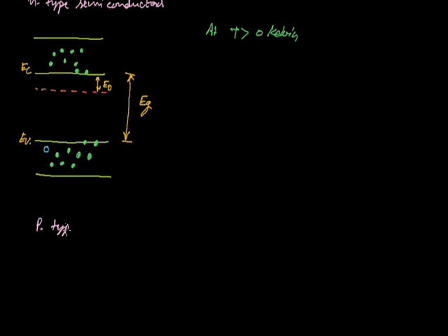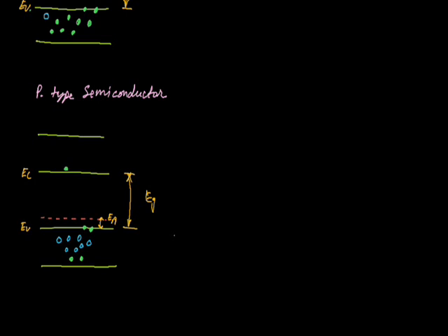In a p-type semiconducting material, at a temperature greater than 0 Kelvin, with a very small supply of energy, an electron from the valence band can jump to the level Ea and ionize the acceptor negatively. The electrons rise up and holes fall down when they gain external energy. At room temperature, most of the acceptor atoms get ionized, leaving the holes in the valence band.